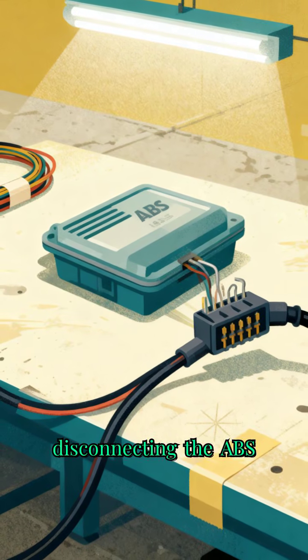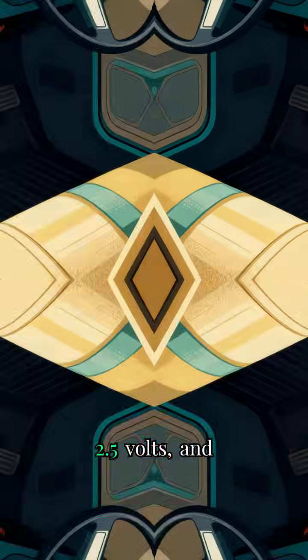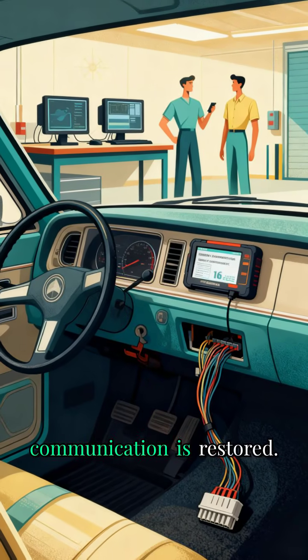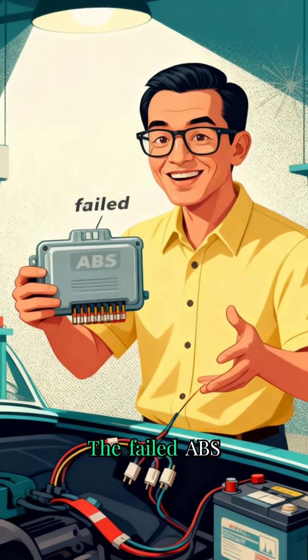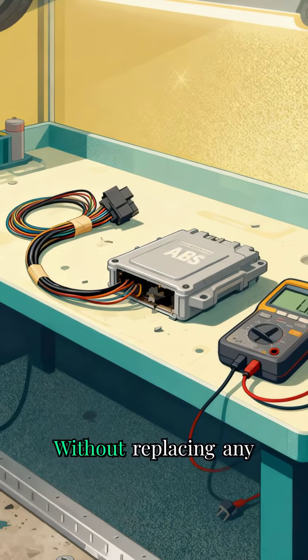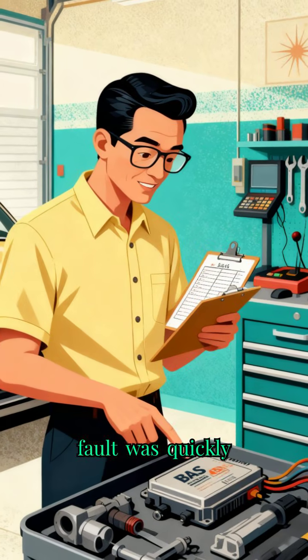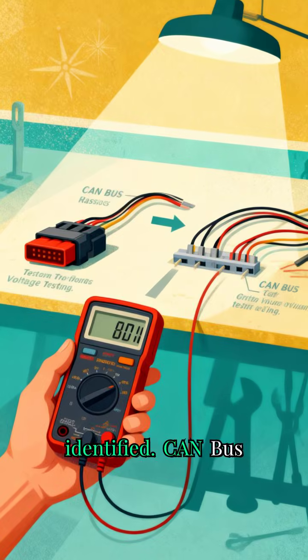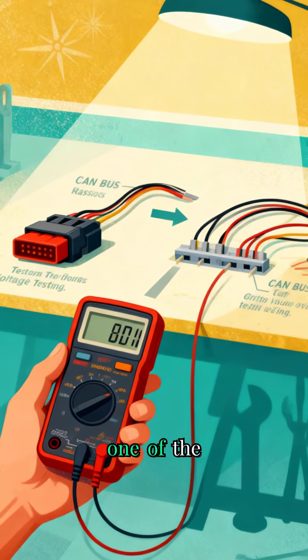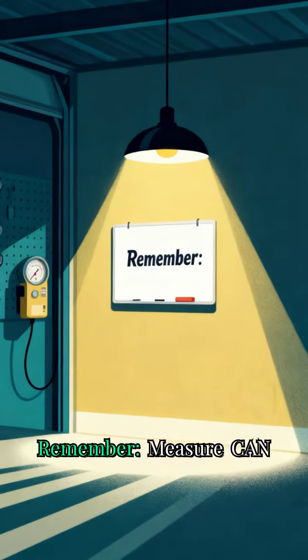After disconnecting the ABS module, CAN low returns to about 2.5 volts and communication is restored. The failed ABS module was pulling the network down. Without replacing any unnecessary parts, the fault was quickly identified. CAN bus voltage testing is one of the quickest checks you can perform on a communication network.